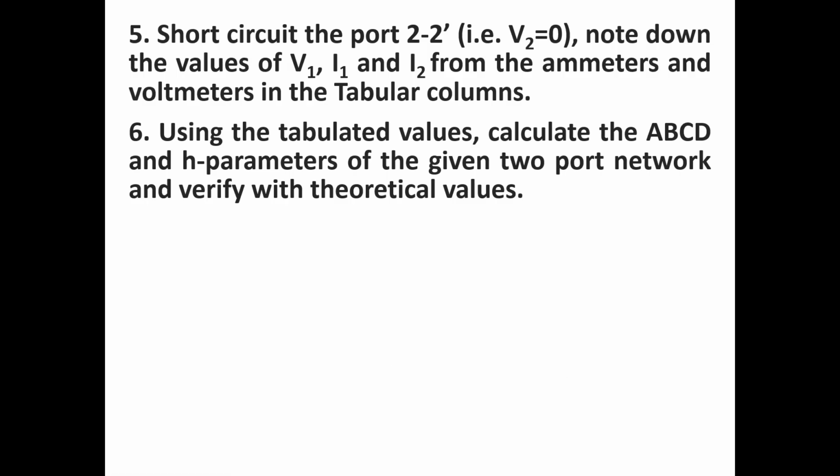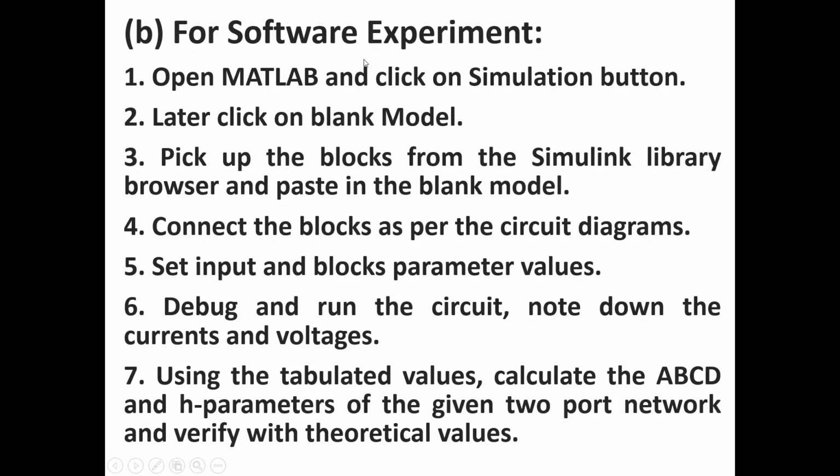Next, let us see the procedure for the software experiment. Open the MATLAB software and click on the simulation button, and later click on the blank model. Pick up the blocks from the Simulink library browser and paste them in the blank model, and connect the blocks as per the circuit diagram, and set the input values, that is, source values, and block parameter values.